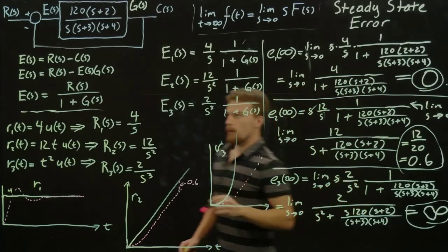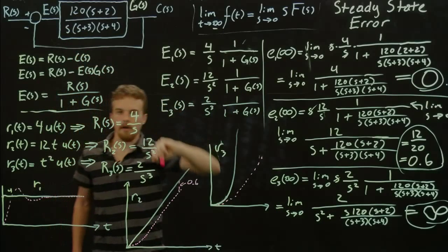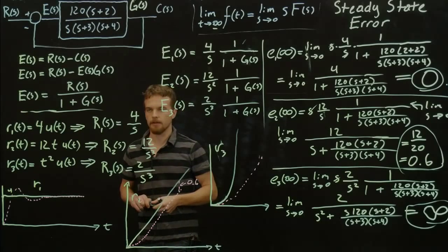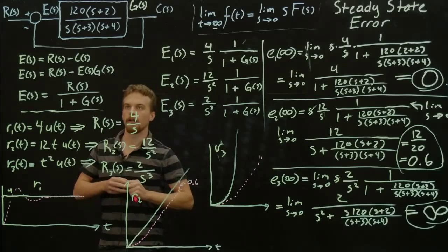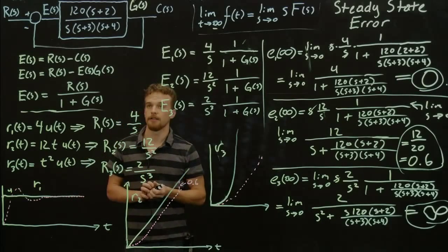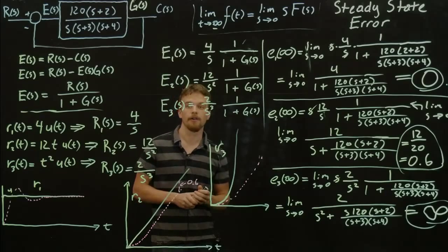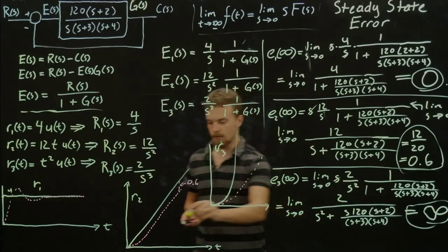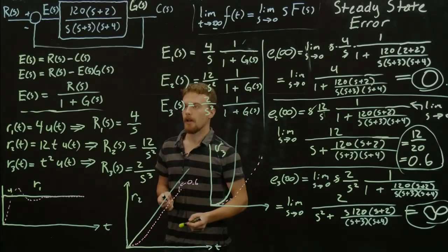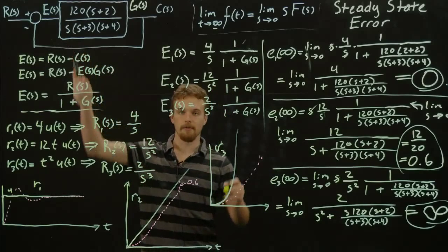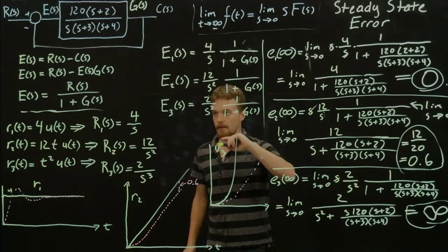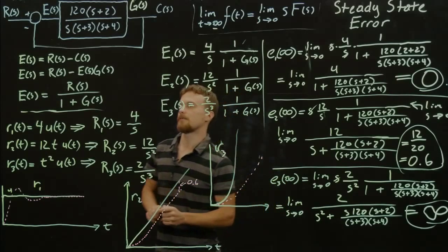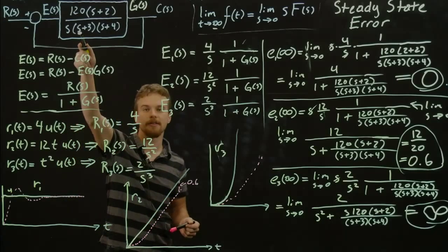So we see that s up here. And what is that? That's an integrator, right? That's a practical thing to be able to put in a system. So if we put 2 integrators in, we'd have s squared here, and we would see that our system could also track this ramp perfectly, and so on and so forth. If we had 3 integrators, it would be able to track this parabola perfectly. So that's a good thing to see from this. I think we refer to that as the type of the system sometimes, the number of integrators in it. So this is a type 1 system. It has 1 integrator.